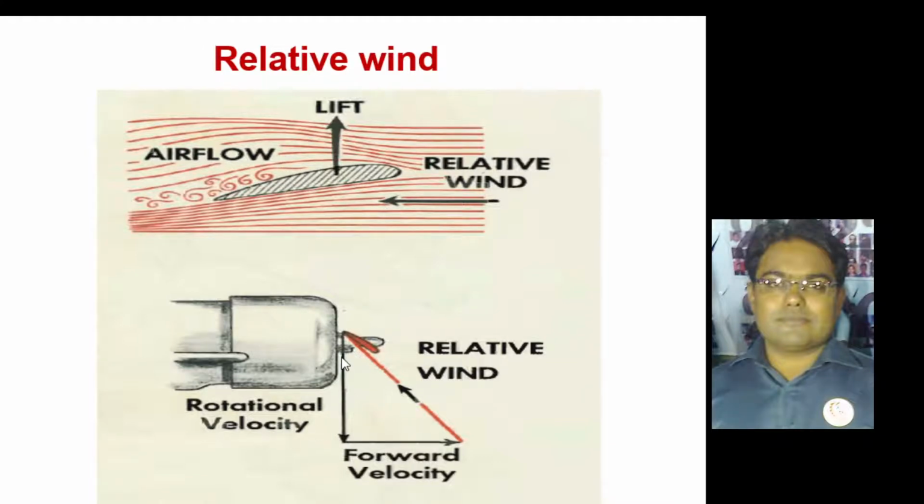So if we look at the propeller which is mounted on the nose of an aircraft engine, particularly when we talk about the piston propeller aircraft, where your propeller will be mounted on the front portion of the engine. So this is an airfoil, right, which is attached to the hub. If we just focus on this line, this is called the center of rotation. About this, your blades will be rotating. So this is the hub, and this is the airfoil shape.